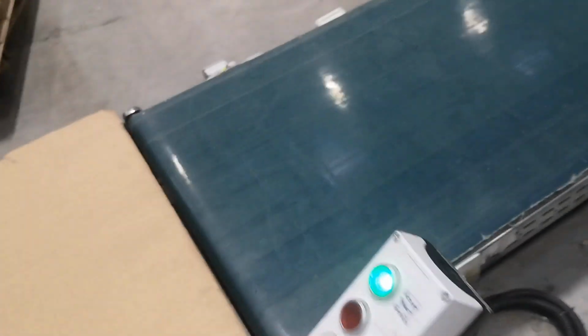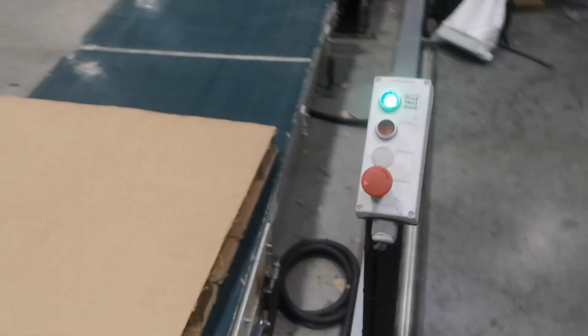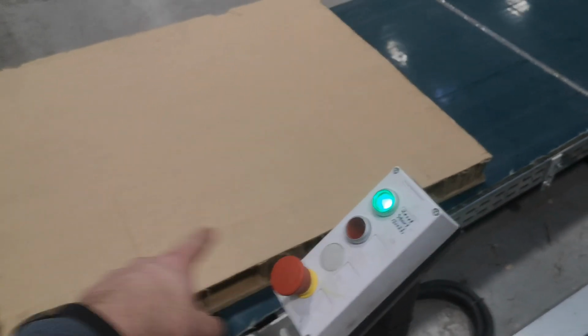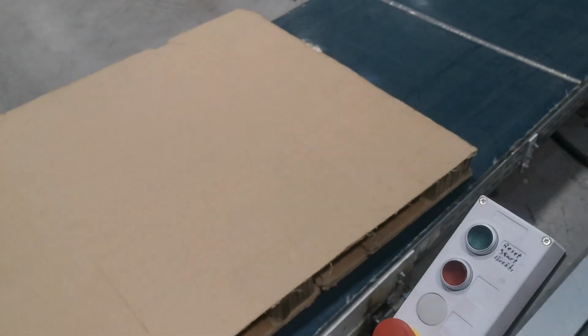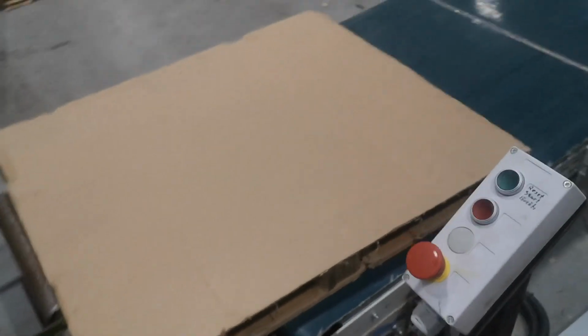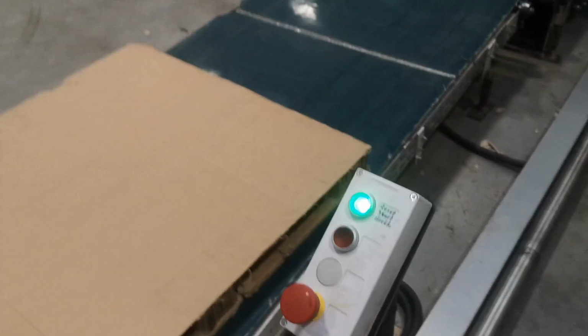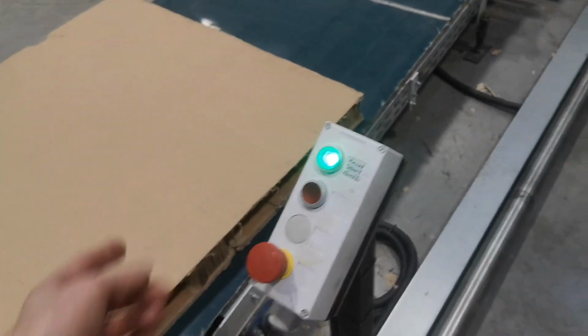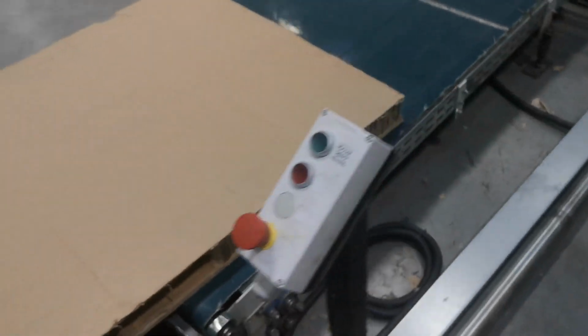And now it's on the sensor. 2 seconds of delay. Okay, I'm going to add it one more time. As you can see, it doesn't go to send state immediately. I have added, when it goes from one conveyor to the other, it works immediately, but if you place the pallet manually, I have a 5 seconds delay.